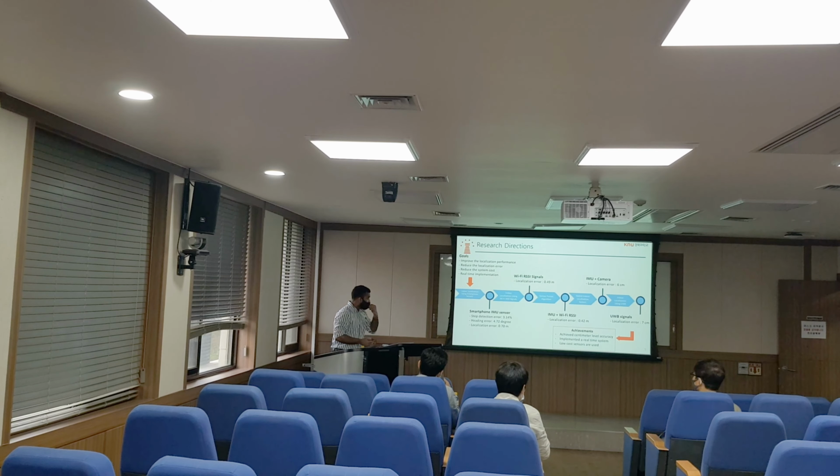Our system has 0.49 meter localization error compared to some conventional approaches. And next, we combined RSSI data and IMU sensor data together in a sensor fusion framework. When we compare the position from both localizations, we have a result of around 0.42 meter, a small reduction in the localization error.